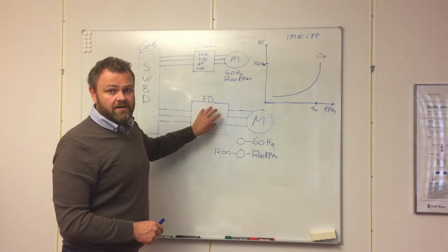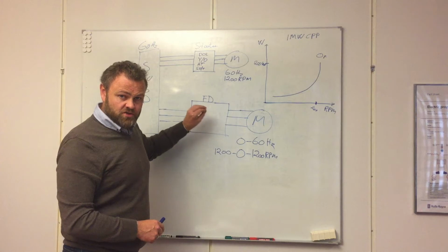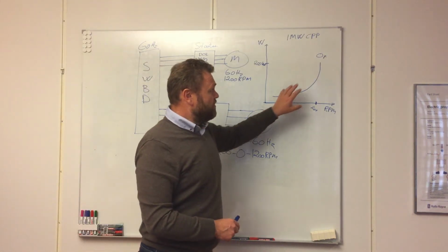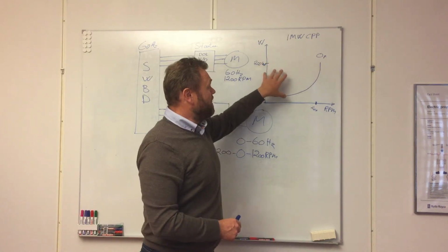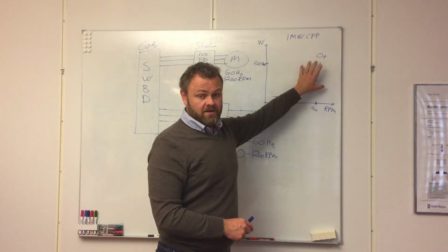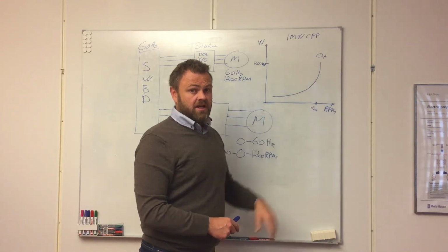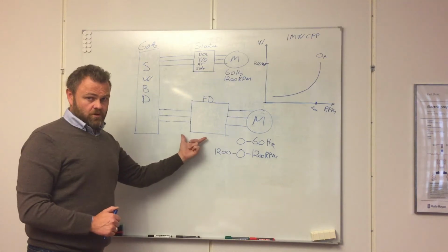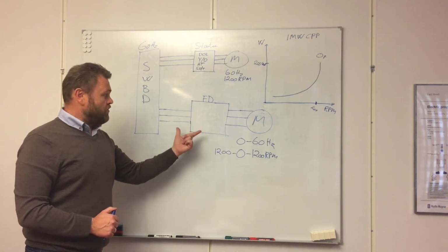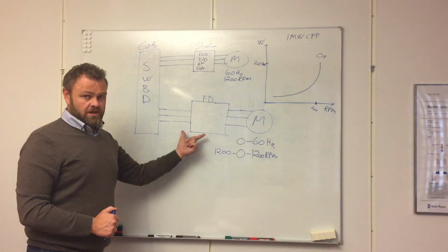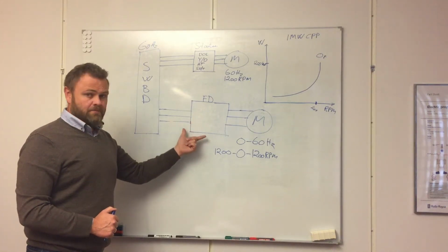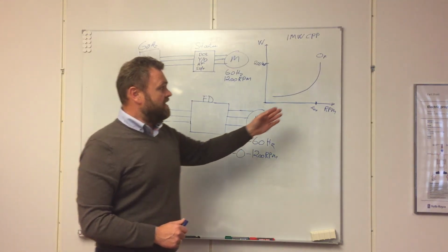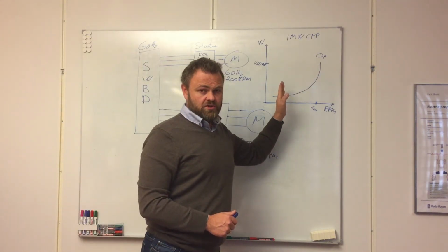However, if you compare the small losses you add with a frequency drive to the losses you have with a propeller, you will in many cases see that it's of huge value to utilize what you have as a capex and invest in a frequency drive, and then bring the operational cost down.